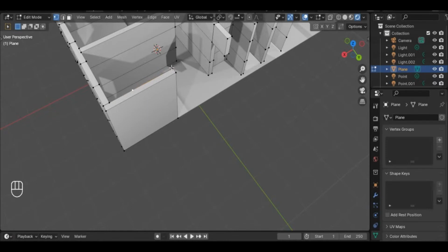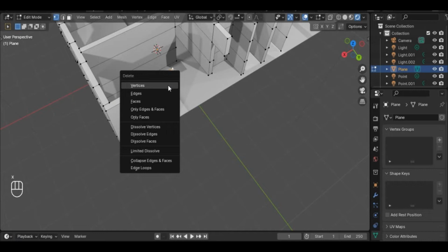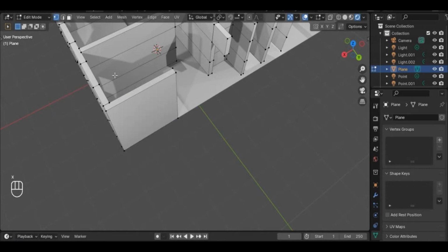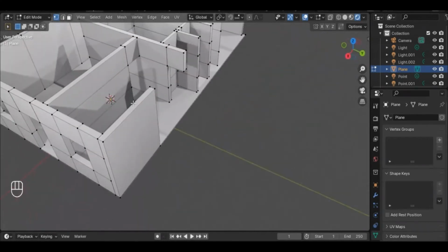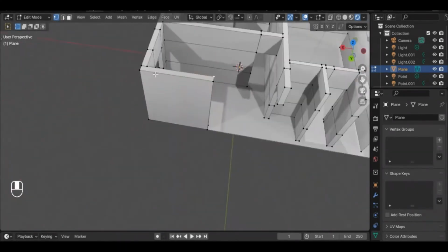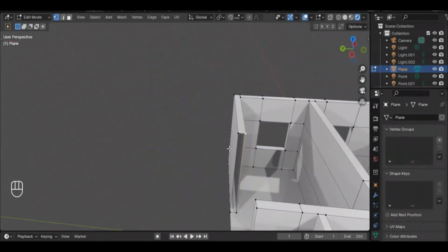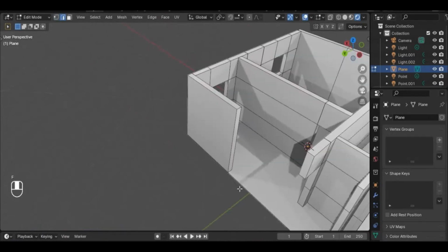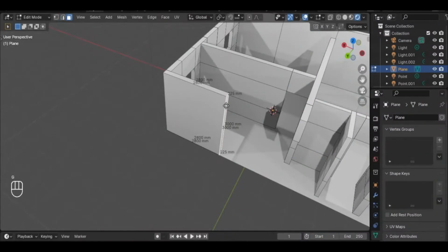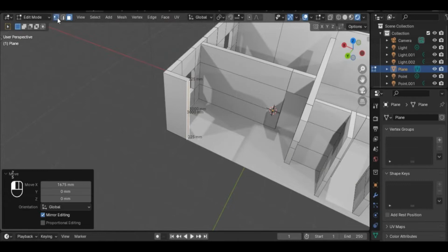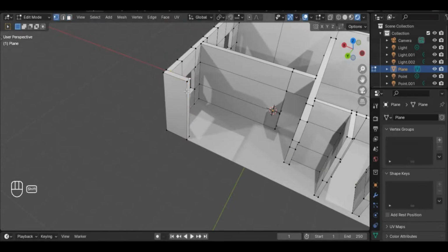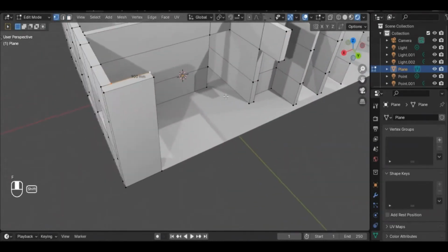Let me first delete this edge. Deleting that edge now makes that vertex I initially had connected to this particular mesh. So let's create a face here. So now I'm moving this one by 1675 on x. So now, when I measure this place, you see that it's going to give me 900. Yeah, can you see? We have 900.